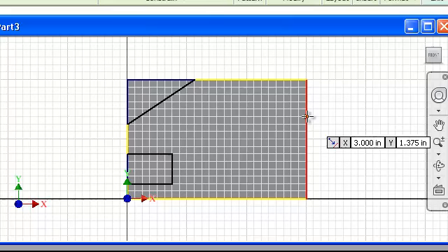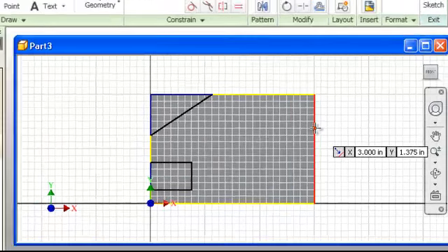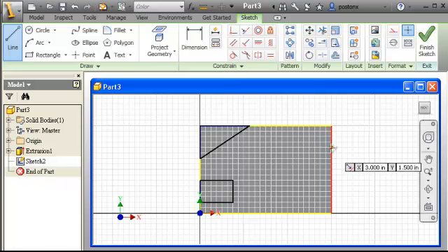Okay, now let's see what we want here. Now we want up our dimension on the drawing. It says 1.5 inches up. Let's go 1.5 inches up. Bonk. 3 inches over. Bonk. Now, click. Now let's go up to the corner. We know that's where we want to go because our steel runs out up there. We can't make new steel.